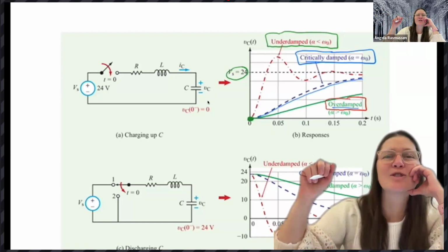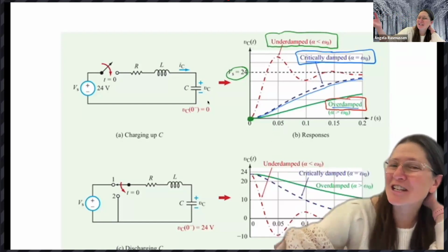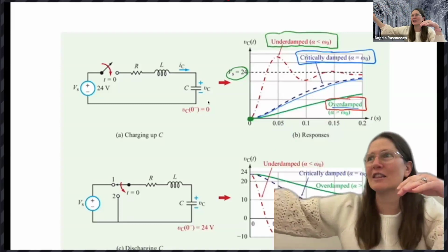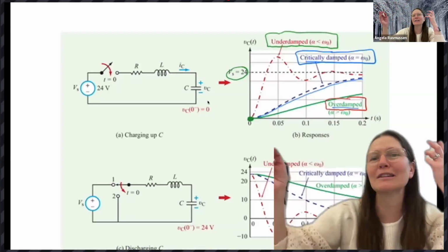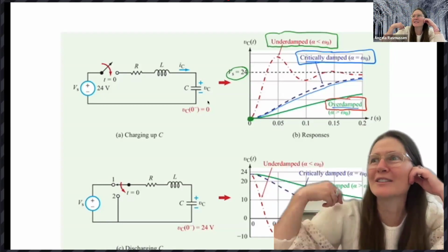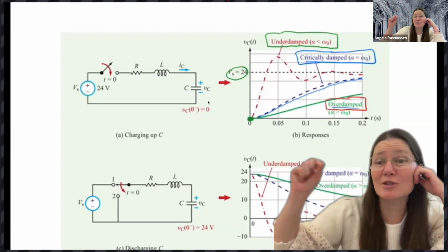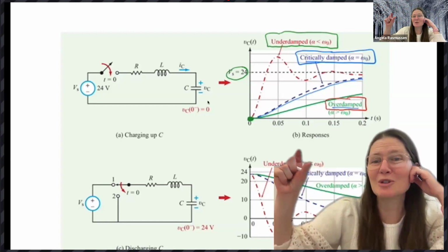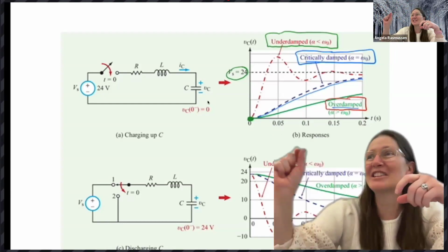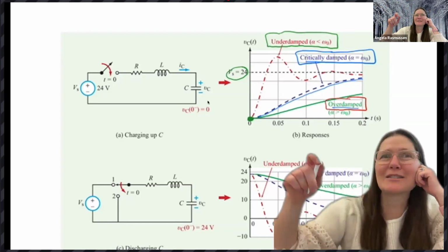The peak of it would actually hit 24 volts, because you can't have more energy in there than you can actually supply. So it would hit a peak of 24, oscillate, and then go close to like 22-ish. You'd probably lose a couple volts in there. Again, we use ideal components that never lose energy. Realistically, they do dissipate energy for many different reasons.